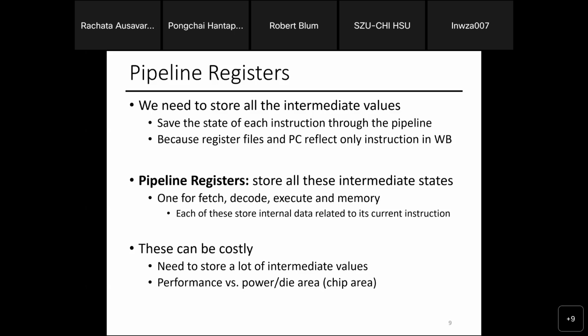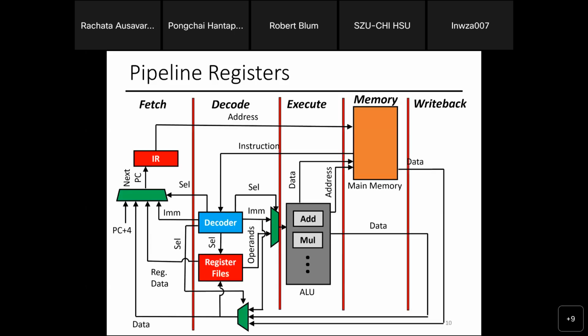But for modern computing devices, the number of stages is really deep. Now, the blue thing I draw here again, sorry about this, should be the PC, program counter. And then the IR should be here, the instruction register that stores my instruction. So the decoder, the execute unit, memory, write back, and the fetch each have their own barrier between the stages that store, think of this vertical red line as a buffer. Whatever data crosses that line, I store in this buffer.